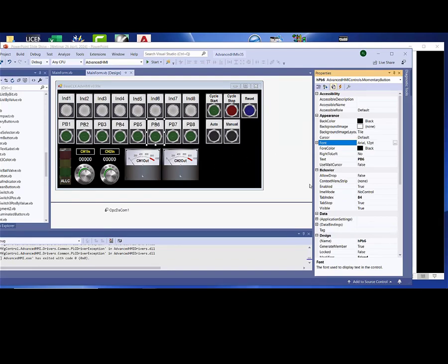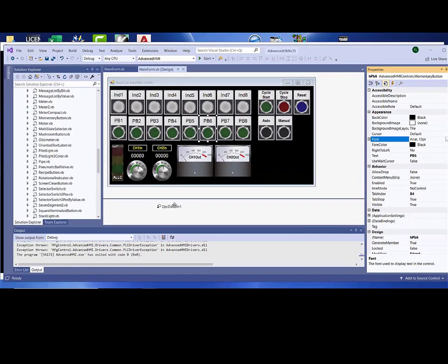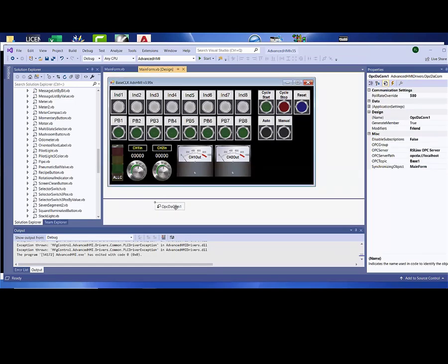So a lot of this stuff, you can get started and do your own HMI pretty quickly. You want to get the driver for the particular HMI you have. In my case, I'm using OPC, which works with about any simulator and a lot of PLCs, right? You just set up an OPC topic. As I showed you before, you have to go into the Allen Bradley driver to set up the topic. You still need RSLinx in this case to set this up. But once you have it, right, there's all the settings for it.